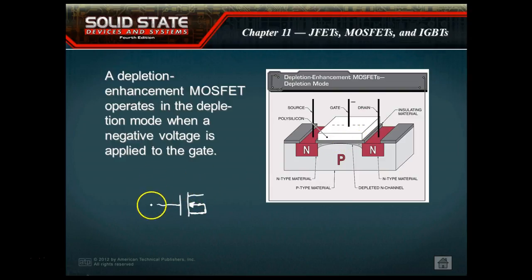And what we can do over here is we use one resistor to bias it. And then we come over here and we would put a common source. We'd put a resistor here and we'd put a resistor there. We don't even need a coupling capacitor on this guy. If I take my output right here, then it's going to be a common source. We can bring AC directly into it.